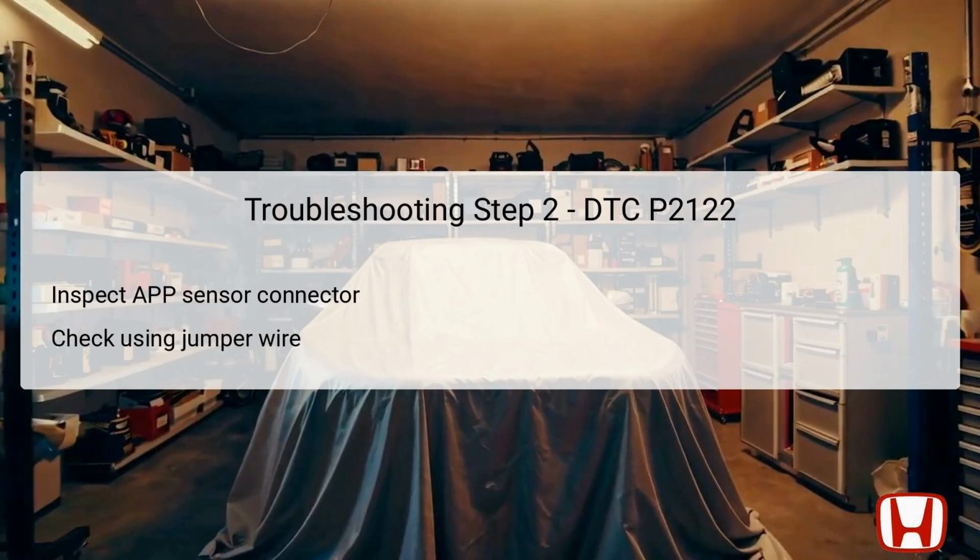Once this connection is established, turn the ignition back to the on position again and recheck the APP sensor A voltage using the HDS. If the voltage reading exceeds 0.2 volts, it indicates that the APP sensor itself is likely faulty, as the components are functioning normally. However, if the reading remains below this threshold, further investigation into related components or circuits must be conducted.